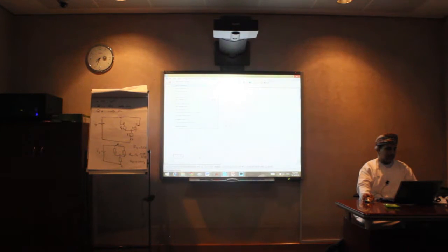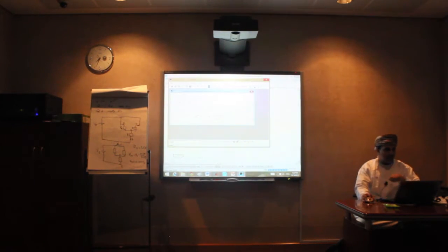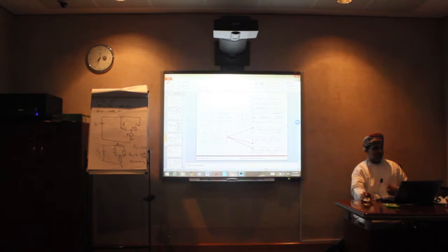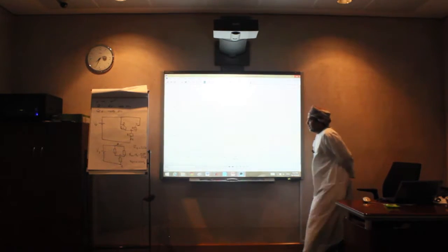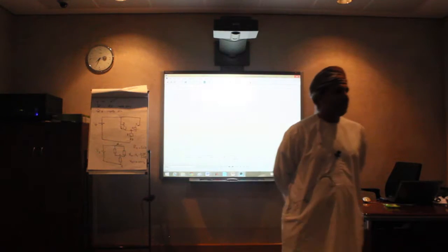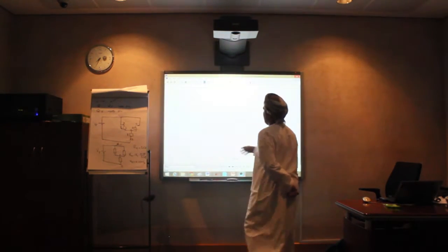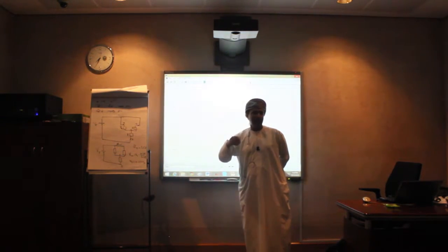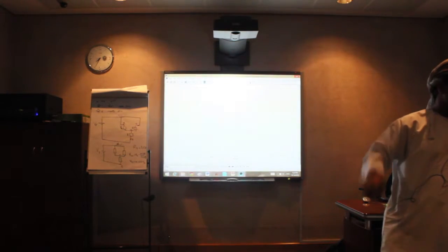So if I run this one, I can see, for example, if I would like to see VAN, I would see it like 6 steps like that, like this output here. So from this DC, I got this signal. You see, it's just 6 steps, but it's AC now, not DC, right? It's AC. Yeah, exactly. So this AC, if I add a filter, I can get rid of those ripples, and then I will get a sinusoidal. We cannot say exactly pure, but at least we will try to reduce or mitigate the harmonics in order to get a nearly pure sinusoidal waveform.